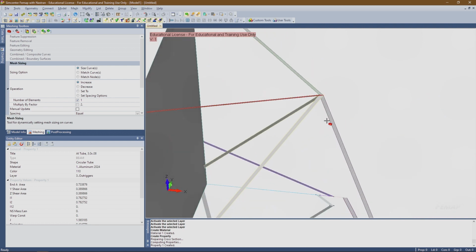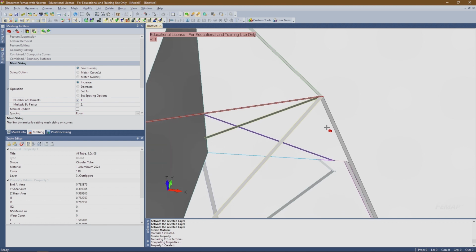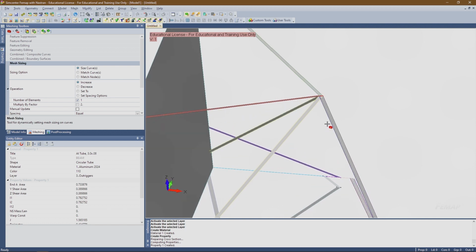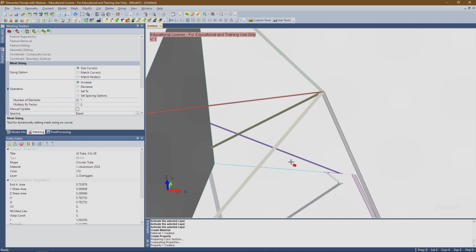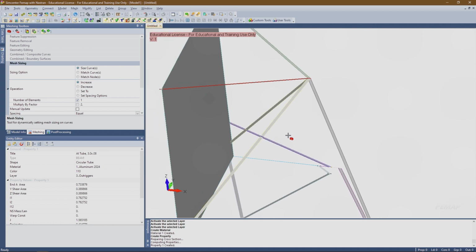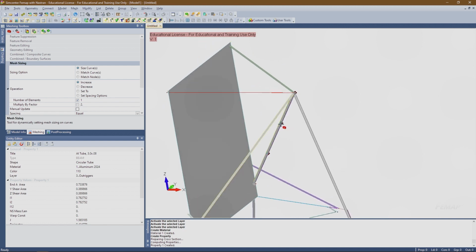The accuracy of a beam is not dependent on the amount of elements that you use by any means. However, if you are doing analysis like buckling or modal, the more elements that you have, the more modes that your finite element model can pick up. Because essentially, if you only have one element, you can't get a sinusoidal wave by any means. So for most of these, like these long struts, I'll probably go with 4. So essentially I'm doing mesh sizing. I'm going to increase to 1, 2, 3, 4. And I'll do the exact same thing on the other side.